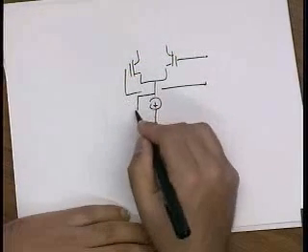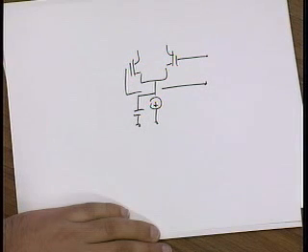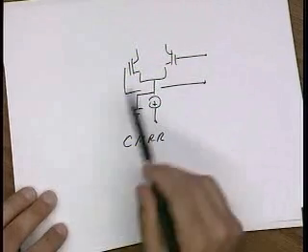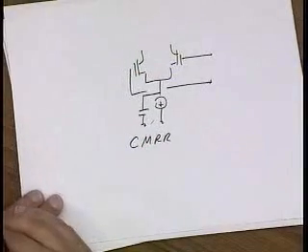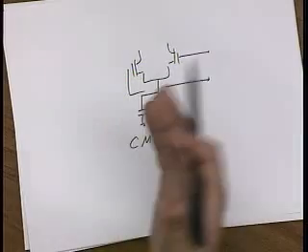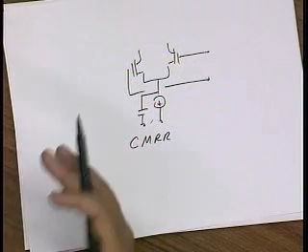Why is it I don't like having extra capacitance on this node? Well, common mode rejection. Yeah. At high frequency, the common mode rejection of the circuit is a function of how much capacitance I have at this point. And if I have this long wire, then there's going to be lots of capacitance. It's that simple. So that's kind of high frequency stuff, right? Not necessarily very high, a few megahertz.